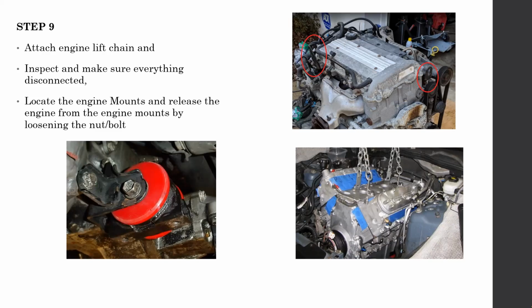It's not an exact thing where the engine mount is. There's no rule that says there will be an engine mount in the middle of the engine. When engines are designed, they try to put the engine mounts as close as possible to places we call engine vibration nodes.